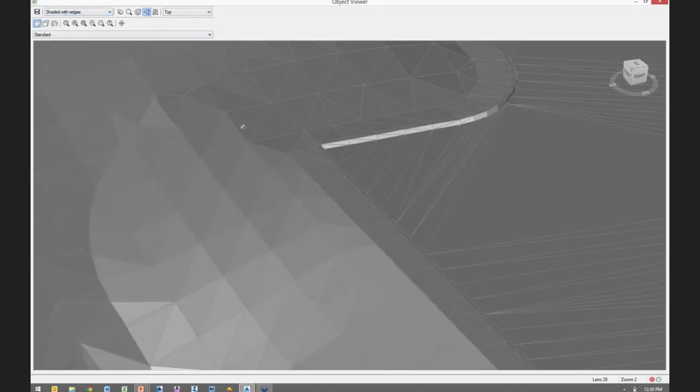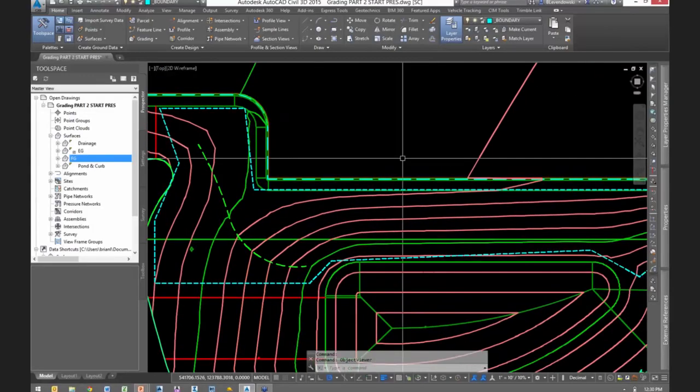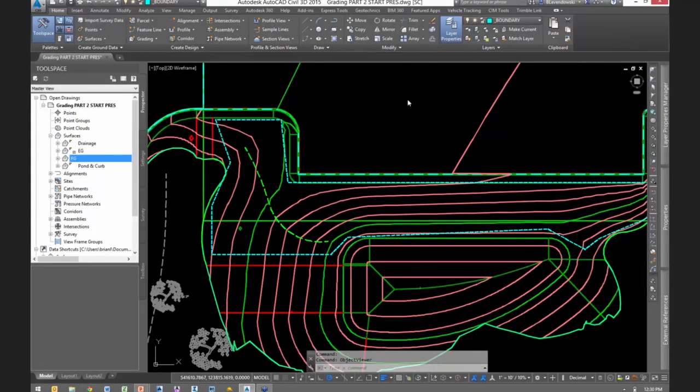But it's dropping a 5 by 5 foot grid and basically chops up all those triangles. When you have smaller triangles, you get better contours. So there's a limit to it though. Don't do it on your whole surface. Your drawing will be huge. Don't need that many triangles, just in areas where the contours are a little screwy.